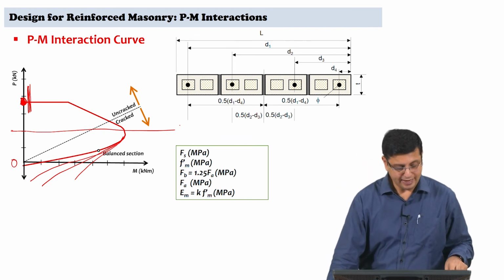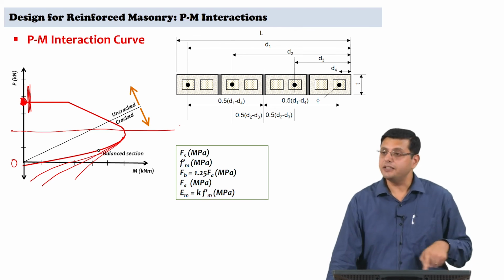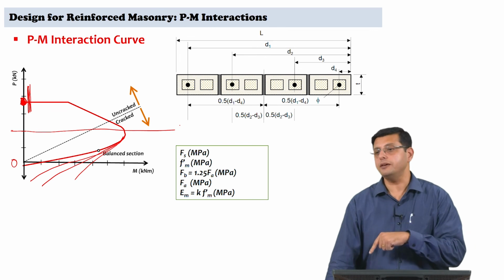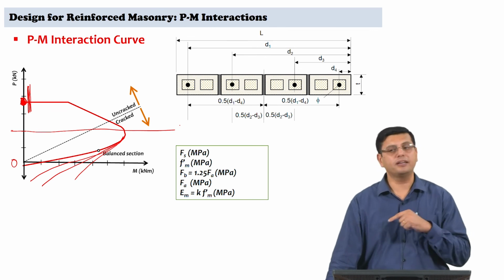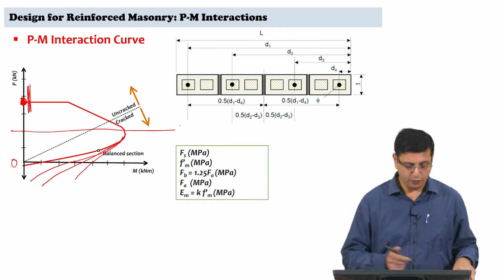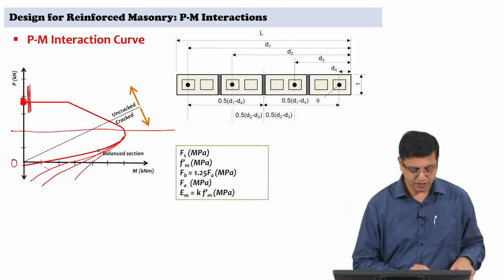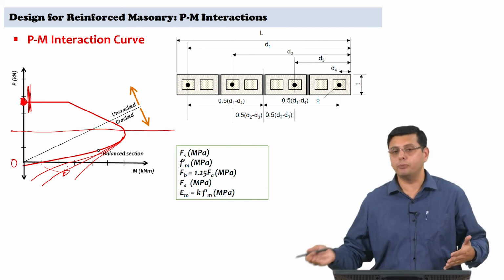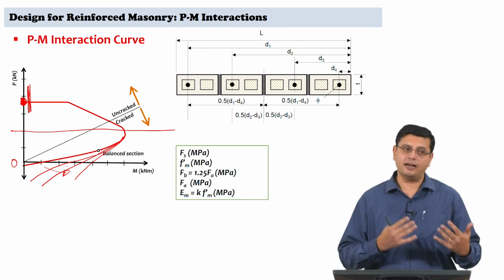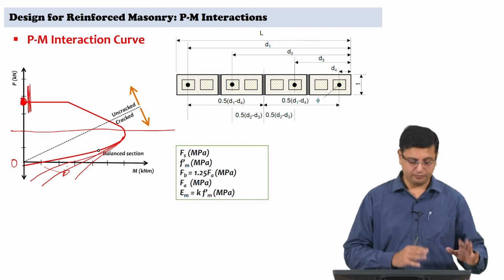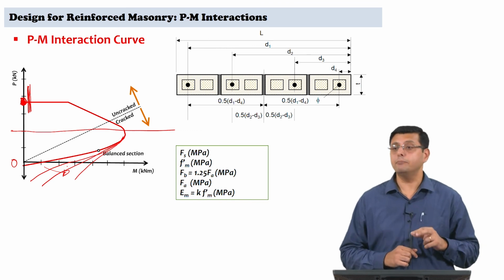First is that it is the region in which the provision of steel reinforcement is going to be beneficial to the moment capacity in the wall or shear resistance in the wall. So, that is the zone where with more and more steel reinforcement that I design, I will be able to get better moment capacities. So, in plane capacities are bound to increase, axial stress ratios are in this zone. That is one thing. The second important thing is,